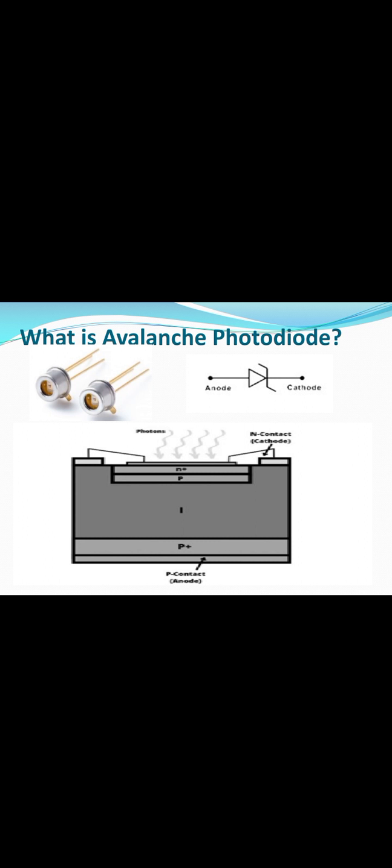These avalanche photodiodes have internal gain, and their responsivity is better than that of the PN and PIN photodiodes. They are more sensitive. With the internal gain, a better signal to noise ratio can be obtained than with an external amplification process. These avalanche photodiodes are used as variations of PIN diodes. These semiconductor materials are used here, with a spectral range for the semiconductors.